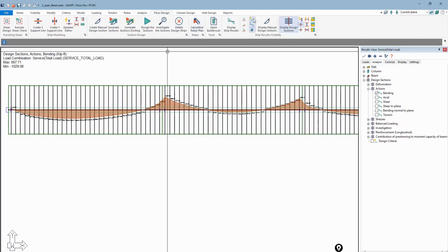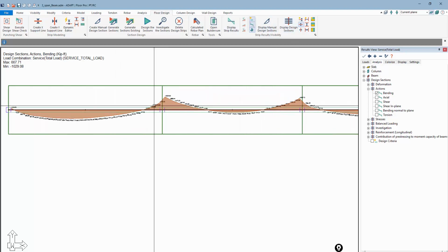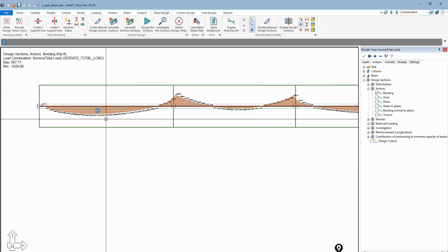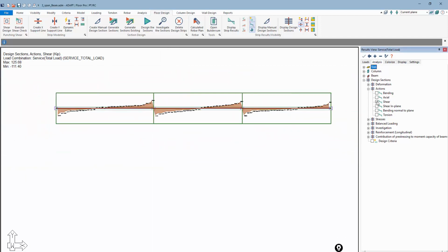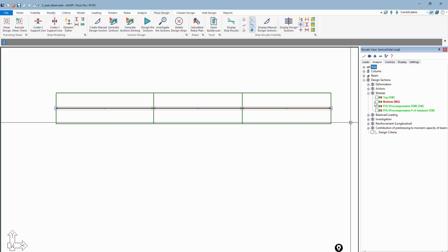And we can turn those on if we use this numerical display on off. This one shows all values. This shows max min values. If I don't want to see all the cut lines, I can turn those off. But this gives us just the moments along the span, moments, shears, axial force, etc. So we could just look at actions. Our real main concern here might be stresses.